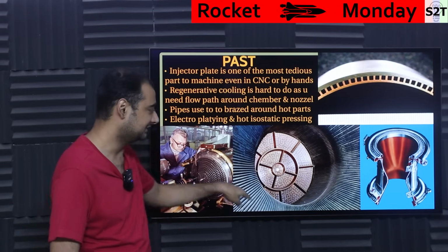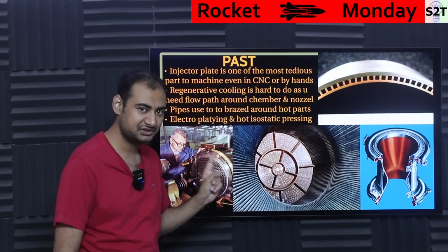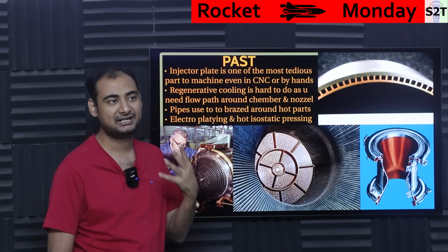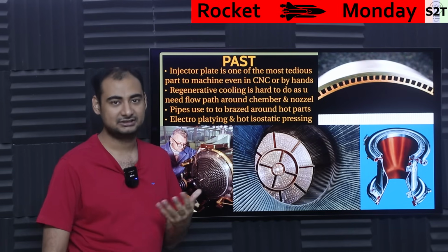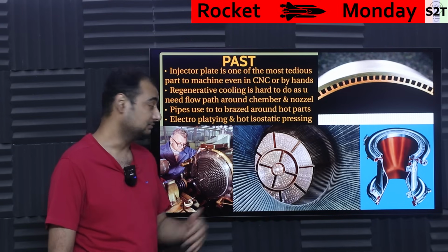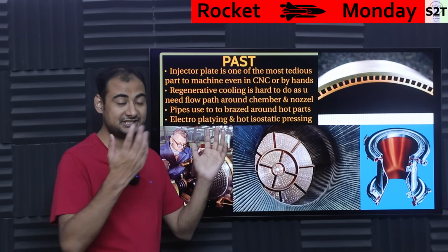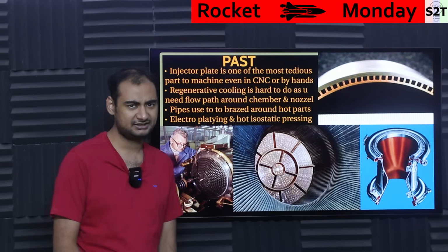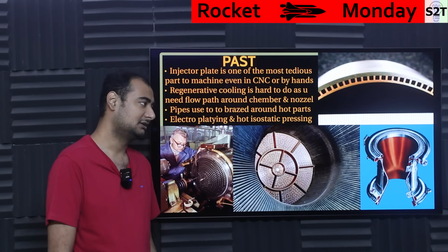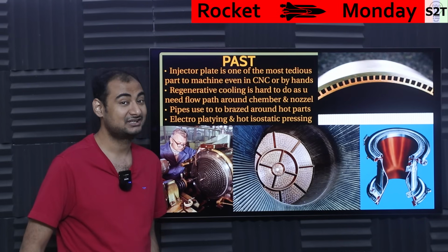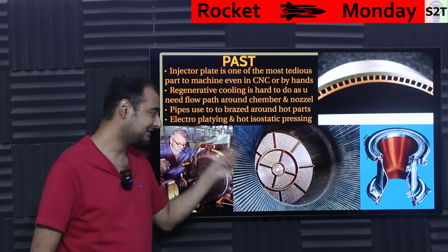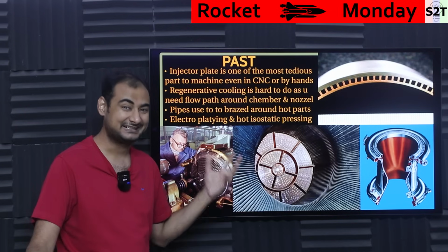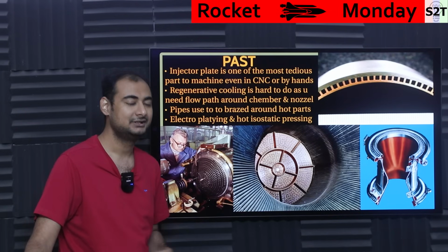Basically, how the heck you deal with this thing. So this is what we call regenerative cooling, because that's the only way where you can have high enough temperature without basically kaputting the engine. You can have graphite on the other end, but it will ablate away. So it will give you a fixed lifespan. Again, suitable for use and throw, but not desirable, and not to mention it does not have that much performance. So for that reason, you generally want to have regenerative cooling that gives you the oomph needed.